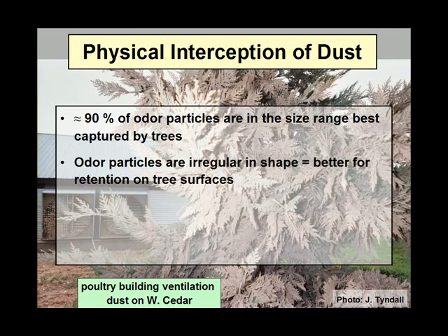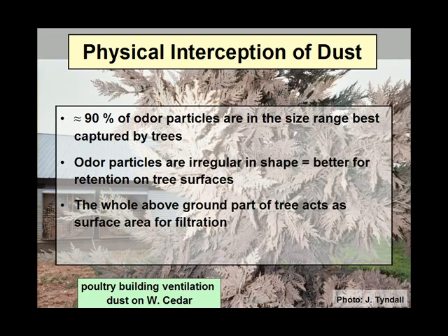Odor particles are irregular in shape, and we know that that is better for retention on tree surfaces, so it just doesn't hit and bounce off. It hits and sticks. And it's the whole above ground part of the tree that acts as surface area for filtration. So it's not just the leaves. So if you're thinking about using deciduous trees that drop their leaves in the wintertime, well, there's still quite a bit of woody surface area there that is also grabbing onto and holding onto different kinds of particulates.